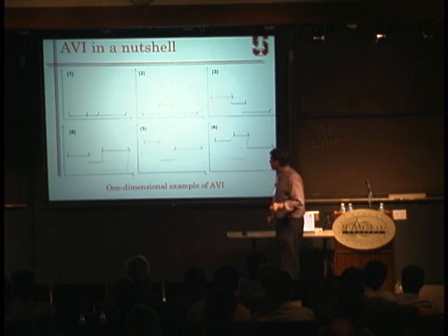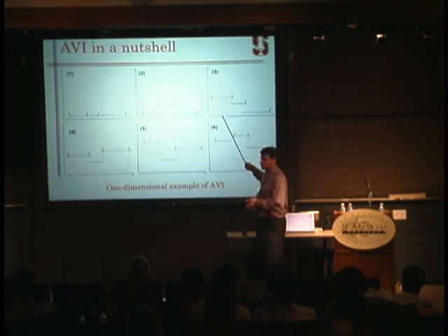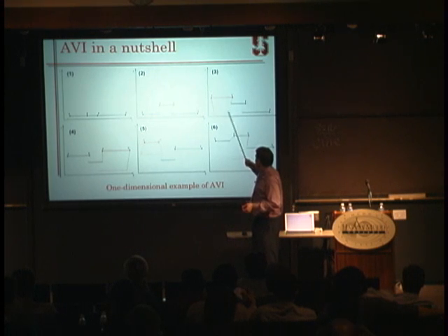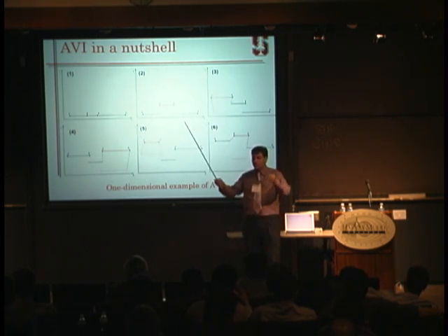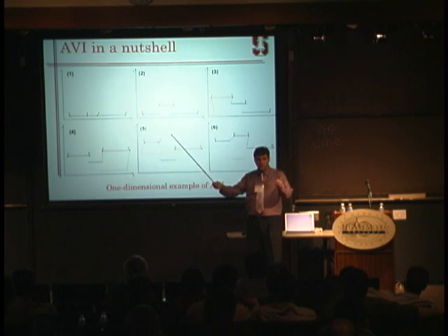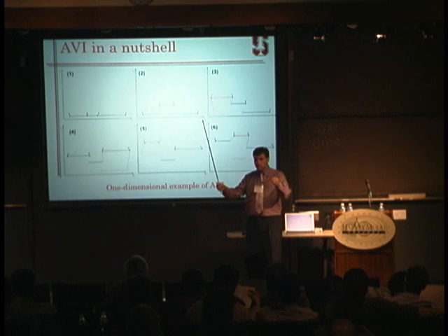Then you take the element that comes next. Let's say this one. You go with the 2 nodes of that element, one that is already here and one that is already here, and you do the time step of that element. Again, you repeat the same thing. Now you have a deformed configuration of your element. This is like a nonlinear elastic spring. You compute the forces, you hit the nodes, you change the velocity, and you proceed.